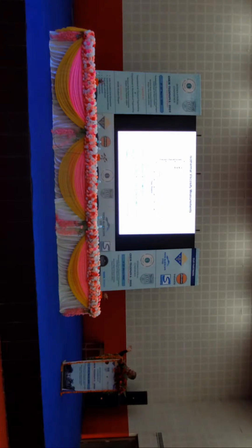So this is how we performed the isothermal viscosity measurements. I kept it at 25 degree, 40 degree, 50 degree, 60 degree temperatures, and you can see that initially there is a reduction in the viscosity. When the curing started, the viscosity shoots up. Next one, please. So this is the degree of cure. Earlier I had done the degree of cure for higher temperatures. So I can extrapolate the kinetic parameters and get the degree of cure as a function of time at different isothermal temperatures, at lower temperatures also. So next one, please.